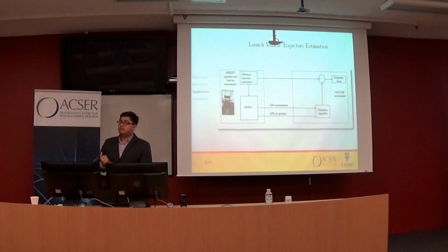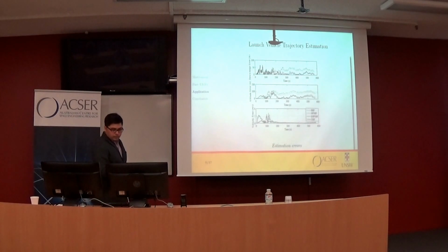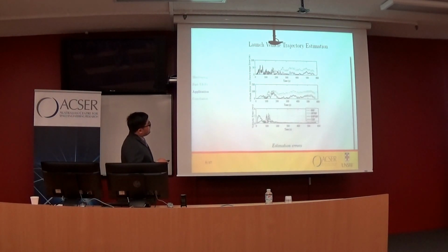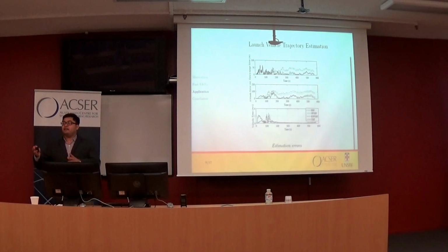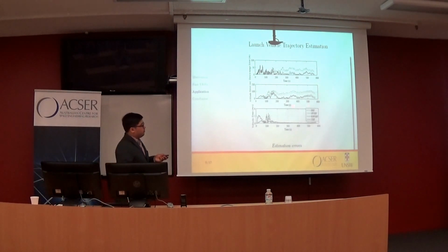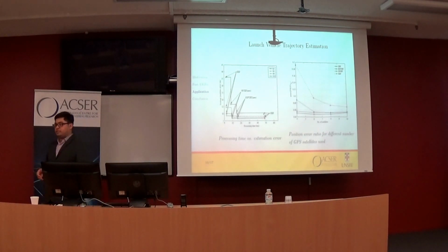We tested the extended Kalman filter, unscented Kalman filter, and the new filters, SPUKF and ESPUKF. So this is the result. You can see that the error for the extended Kalman filter is here, and the unscented Kalman filter is here. SPUKF reduces the error a bit. ESPUKF almost matches the unscented Kalman filter. So definitely the new filters have better performance than the extended Kalman filter, and ESPUKF is almost similar to the unscented Kalman filter.